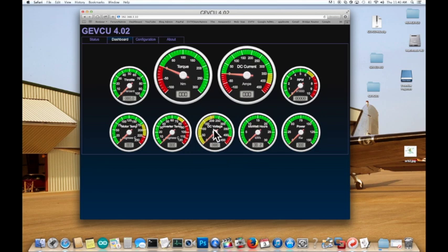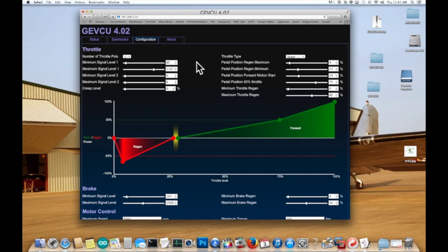You have a voltage you can enter that's your fully charged voltage. Then after you charge the battery pack and you get in, if the voltage is above this value, this will reset to 0. And you set it at some high value that it immediately falls off of when you start to drive. Here is our configuration screen, the main thing, and this is our throttle diagram.